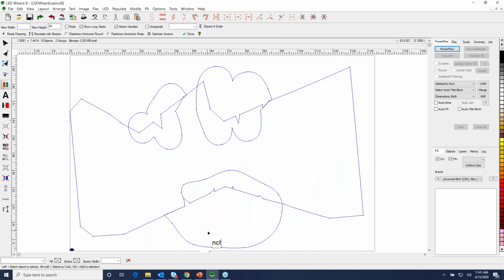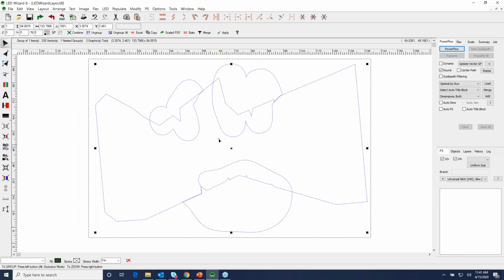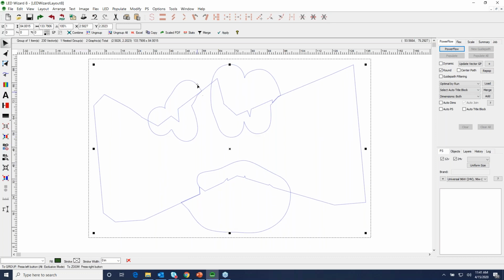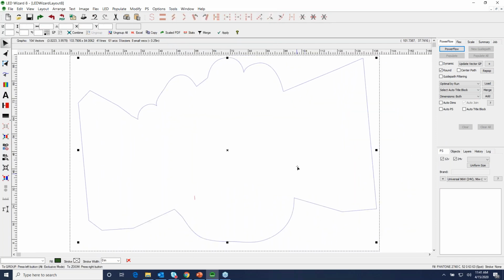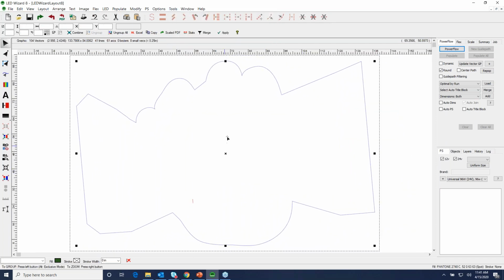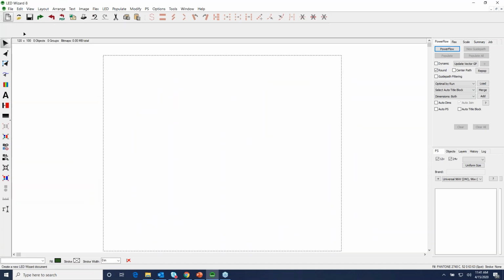Extract and scale. Here's my artwork. Again, that's converting it to lines and arcs. That's fine. So click on done. Okay. And here's how it comes in. And this one actually requires really one more step because I want a single outline. Okay, I can just weld this, right? Welds out those internal objects. And so here's now my overall object. Okay, so that was a pretty easy one, I guess.